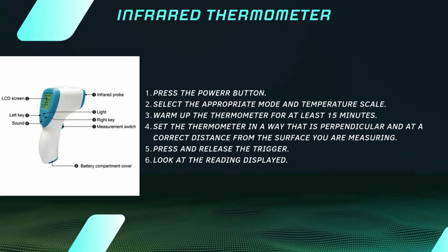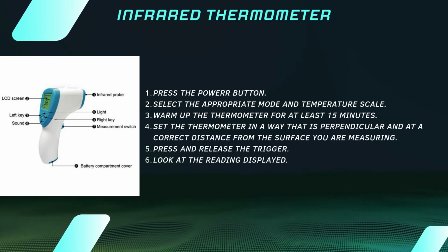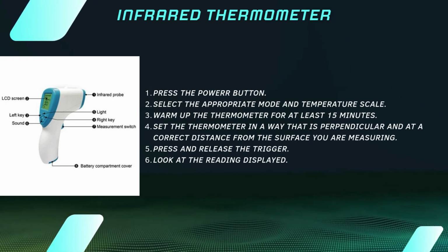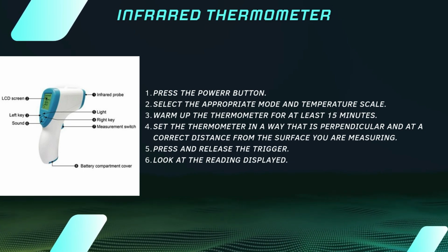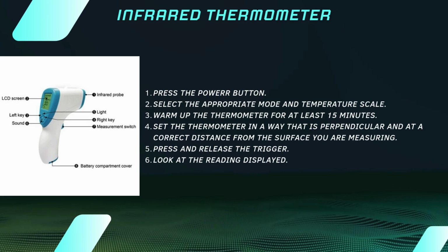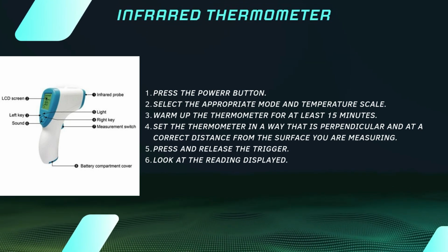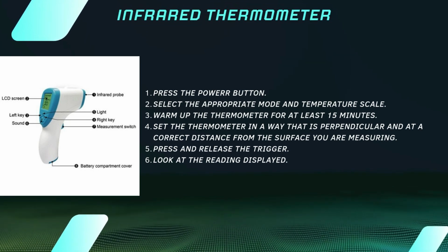Press the trigger, release, and look at the temperature reading displayed. It should be important to consider that the tool has to be clean and free from scratches. Another consideration should be to avoid direct sunlight, excessive perspiration, steam, or dust as they harm the accuracy of the